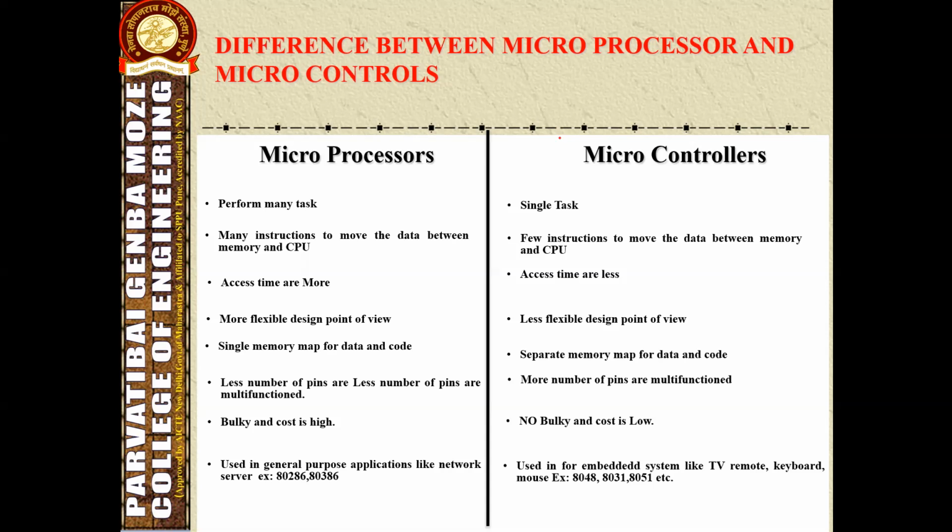The microprocessor contains ALU, general purpose registers, stack pointer, program counter, timing, control circuits, and interrupt circuit. A microcontroller contains the circuitry of a microprocessor and has built-in RAM, ROM, I/O devices, timer, and counter. A microprocessor is suited to processing information in a computer, but the microcontroller controls the I/O devices, requiring the minimum number of components.